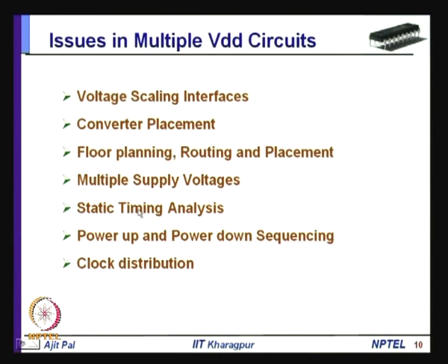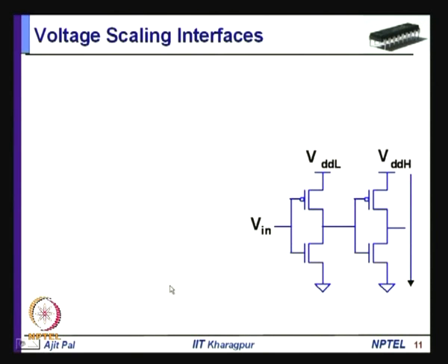And then static timing analysis will become more complicated whenever you go for multi-level voltage scaling. Then power up and power down sequencing, whenever you turn on and turn off the power, will also become difficult, and you have to solve that problem. Then clock distribution will also be challenging in multi VDD circuits. So, let us consider one after the other. First, let us consider